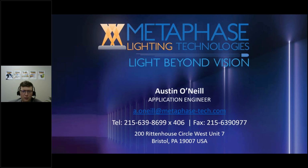Would you say you can get more intensity by strobing the line light? So yes, you can, but it does come with its limitations, given that you have to account for the duty cycle, or basically how much the light is on compared to how much the light is off. As I mentioned earlier, applications where you have to switch wavelengths are certainly where strobing can come in handy. But you can definitely get more intensity, but you do have to factor in that duty cycle. Typically, line scan applications are running so fast that your duty cycle just would not keep up and you would overheat the light. But I have seen applications where you can get that more intensity, and that's also where controllers come in handy too.